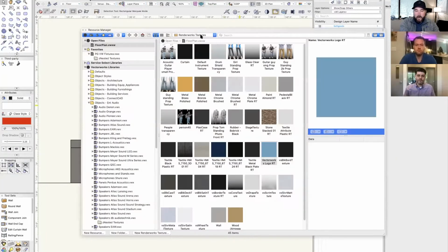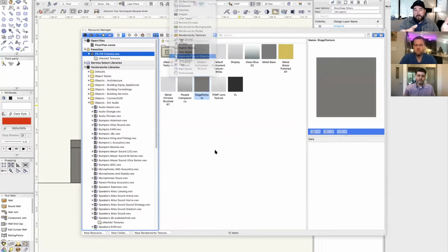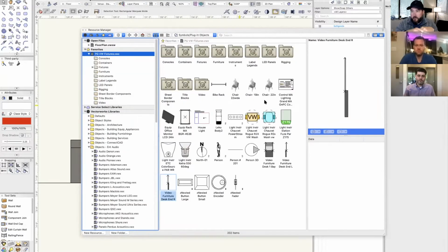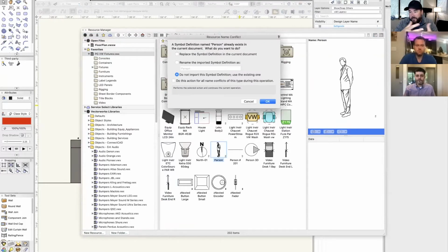You're absolutely right. And in those scenarios, a lot of times what we can do, especially early on, is that can be designed to be a slab on grade. So everything that's in that rear or upstage part is all on grade. So they backfill with dirt, or they fill in with actual material, so that you're not actually having to build the stage up with concrete. You're building it up with actual ground, actual dirt.